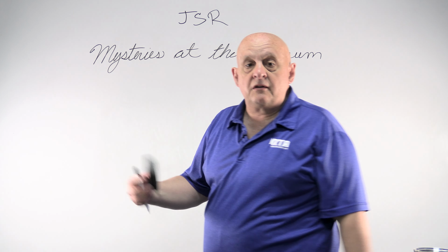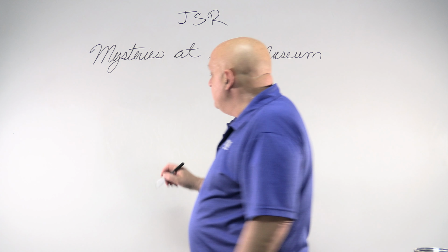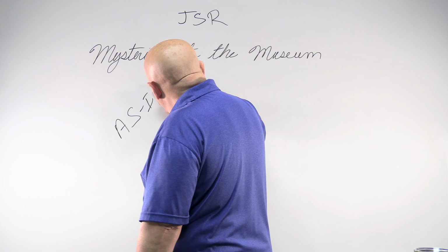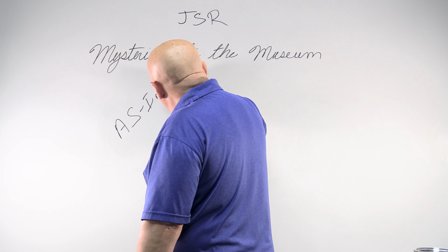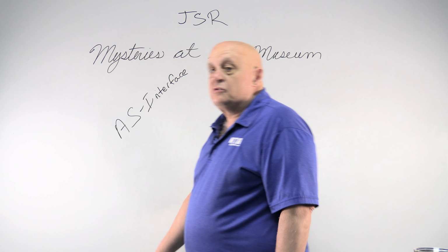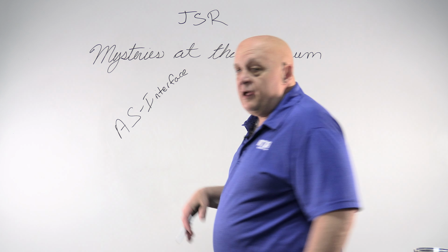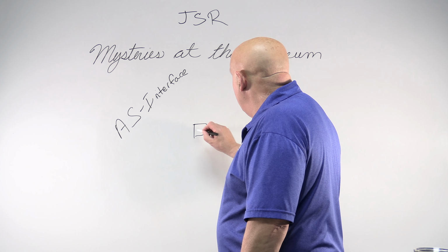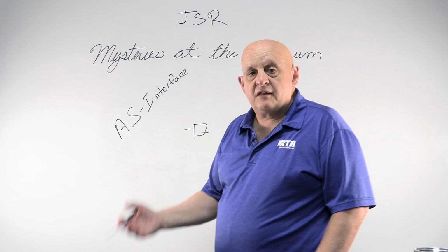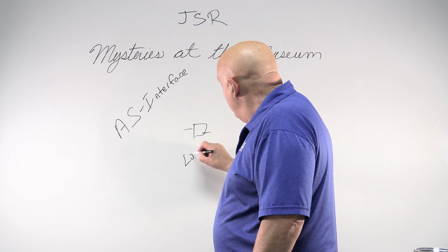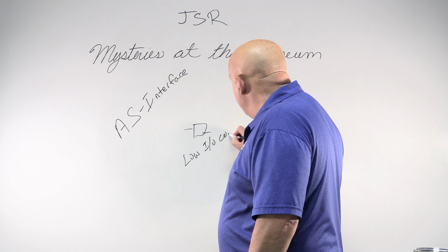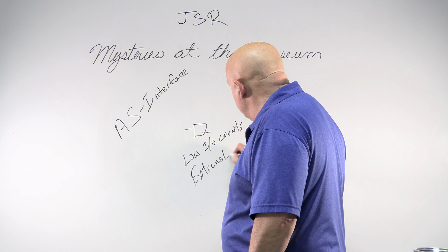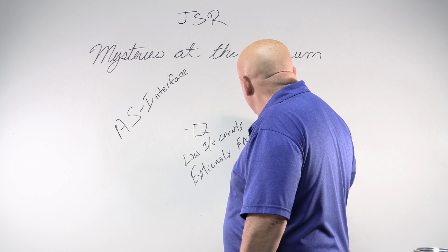Let's digress a little bit, and let's go to something called a hardware replacement network. That's something called AS-Interface, or ASI. AS interface was just like what I said, hardware replacement. Instead of having a bunch of pieces of hardware with direct I/O connections, you could just connect them all up to the bus. Now this was just for very low I/O counts. So you could only have a few I/O points here, but it was extremely fast, on the order of 5 milliseconds to get data.